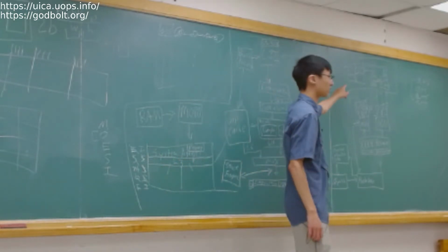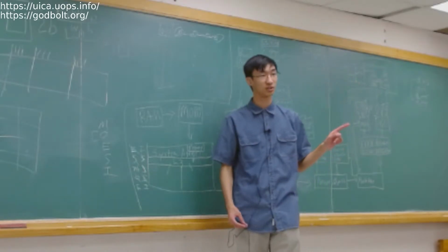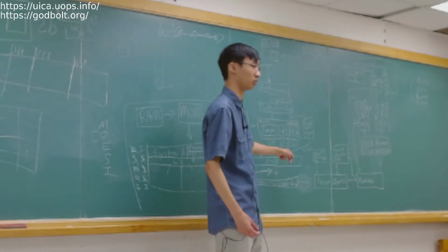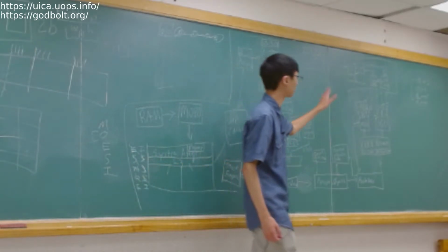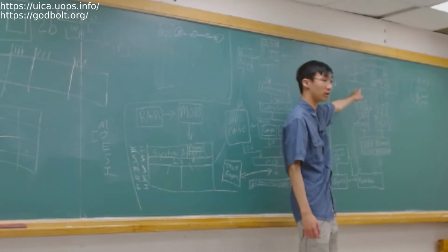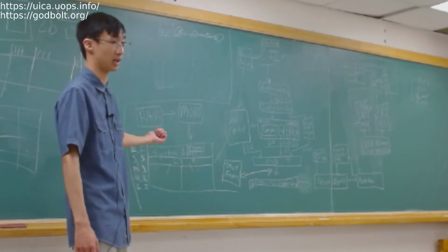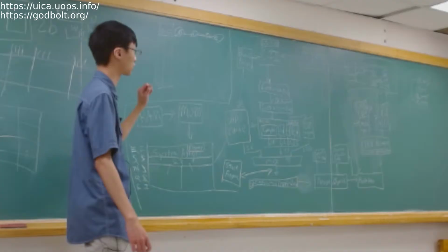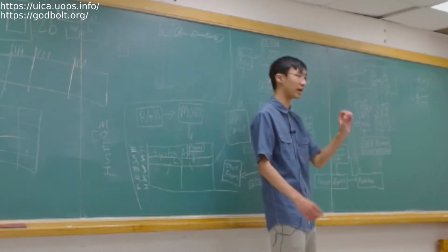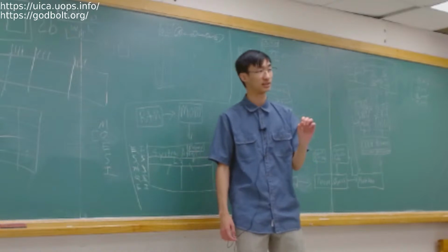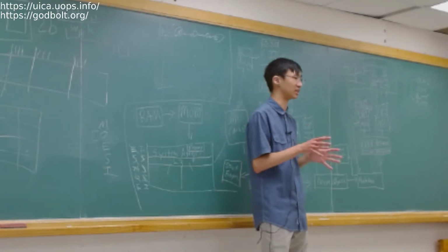Do you think what's in the L1 data cache matters to the execution of the code? No, that's correct. The functional requirement says that this L1D cache does not need to exist at all, and you could go to the RAM every time. It's just a copy. So the state of L1D does not matter, which is why Intel did this one optimization that kind of made this really suck.